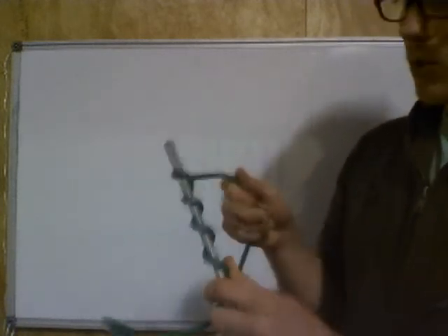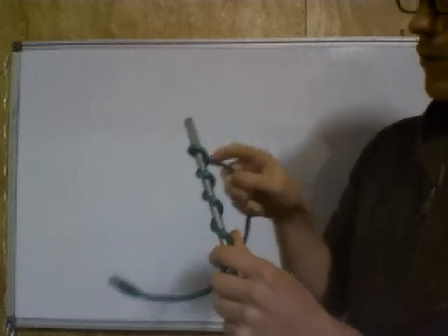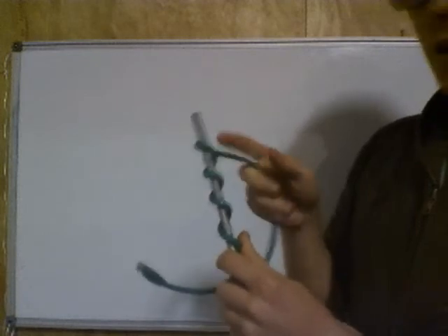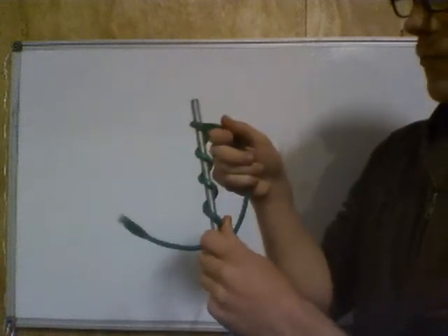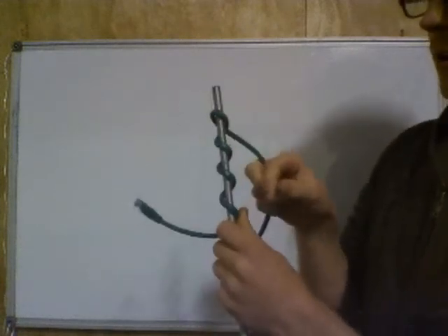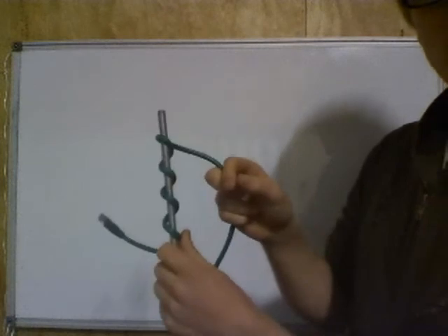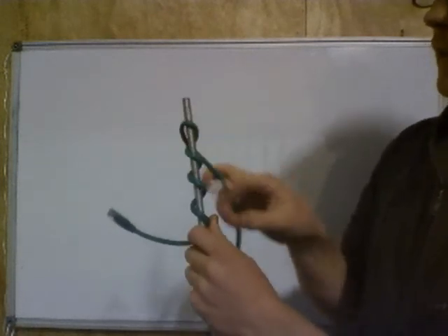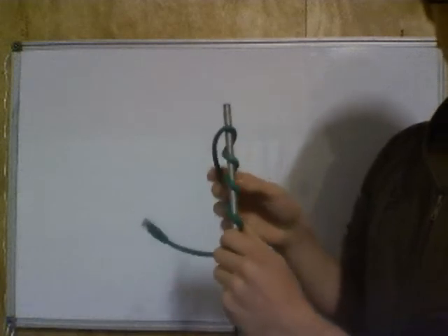And what this actually does is, when you feed an alternating current through this wire, it creates an alternating magnetic field. And then if you get another completely different piece of metal with a bit of wire wrapped around it and you bring it close to your original wire, the alternating magnetic field created by the first wire creates an alternating current in this second wire.